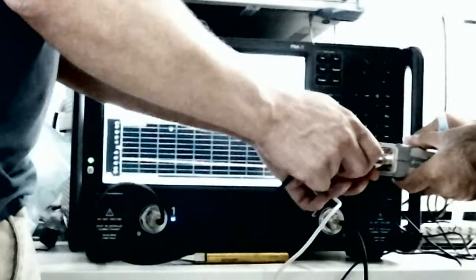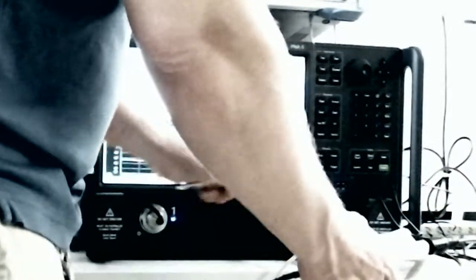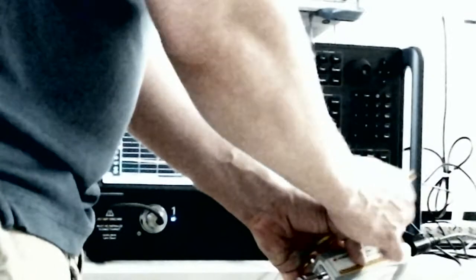Have you guys used a power sensor before? No? Okay. Most power sensors, if they come with an external power meter, this one here has its own little calibration because it's USB, so I'll just hold on to that, are calibrated at 0 dBm, just so you know. That's the reason why it prefers to do the calibration at 0, but you are free to do it at any power level you want.